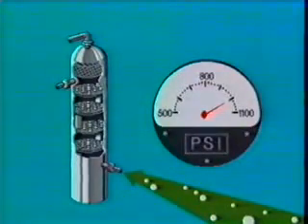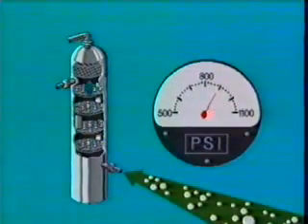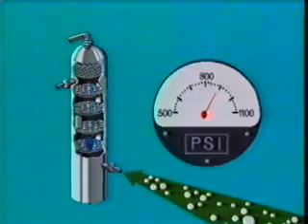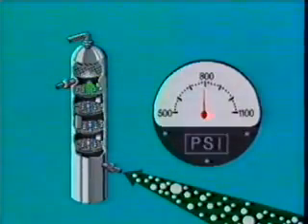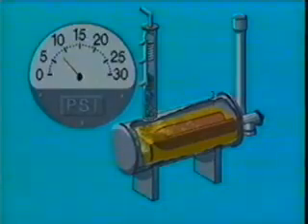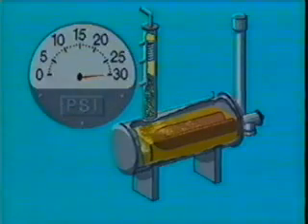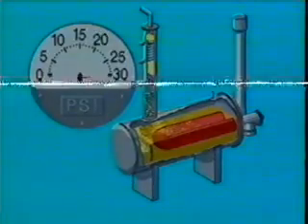First, at constant temperature, water content of inlet gas increases as pressure decreases, causing the unit to work harder to dry the gas. Secondly, at constant gas rates, the gas velocity through the contactor increases as the pressure is decreased, causing carryover problems. Regenerator pressure will build up if there's a plugging or flooding problem in the still packing. An increase in regenerator pressure prevents some water from boiling out of the glycol, requiring higher temperatures in the reboiler. This wastes fuel gas and can lead to glycol degradation.